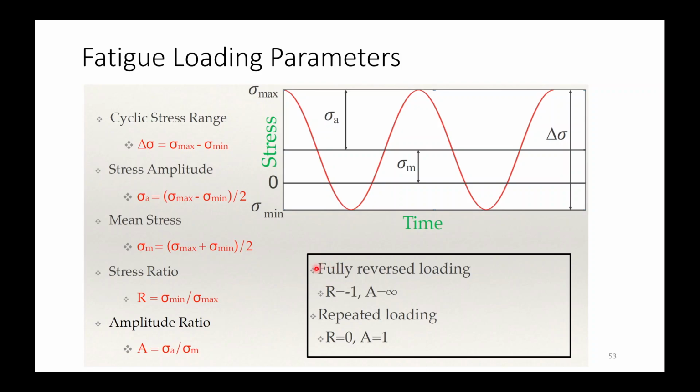In case of your fully reversed loading, you will have stress ratio R as -1 and amplitude ratio A as infinity. And in case of repeated loading, you will have R equal to 0, and A will be 1.